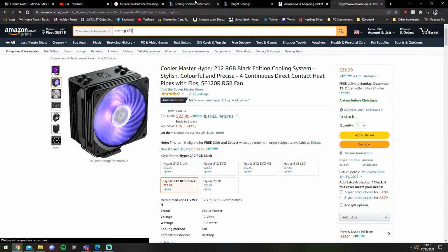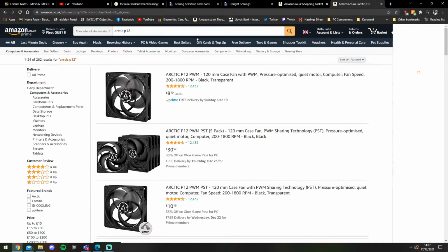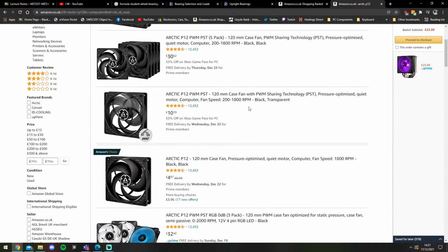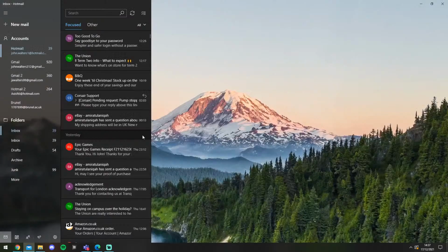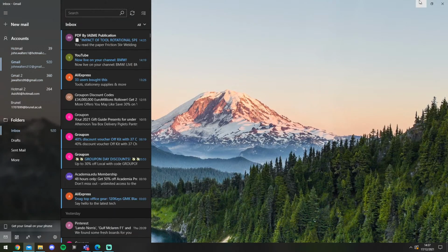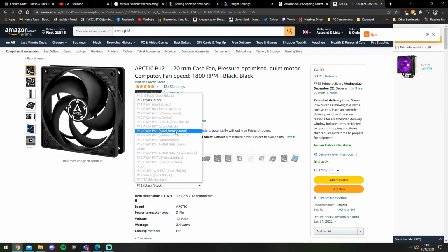As shown some slides ago, at the very end of the radiator package, there is a fan to suck the air from the radiators and release it again to the environment. And this fan is only effective until a certain velocity. Until reaching, let's say, 80 or maybe 90 kilometers per hour, this fan might achieve an additional airflow.